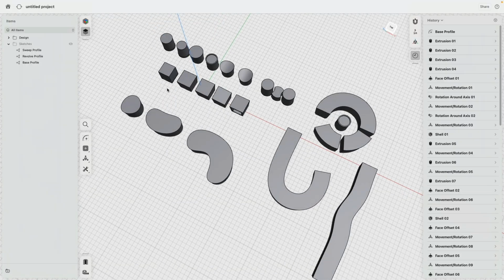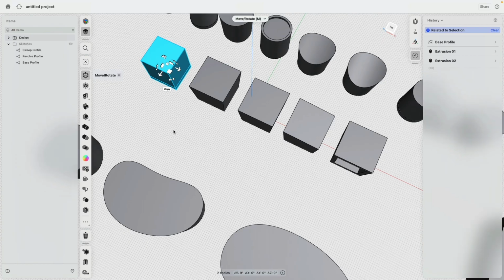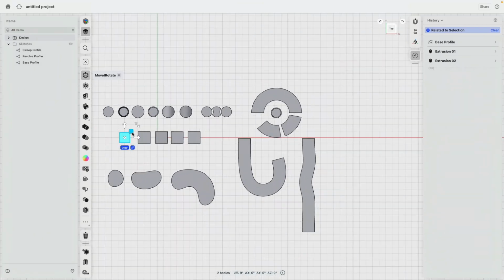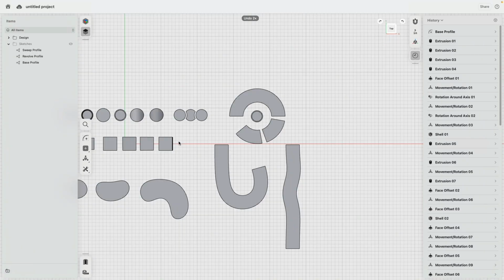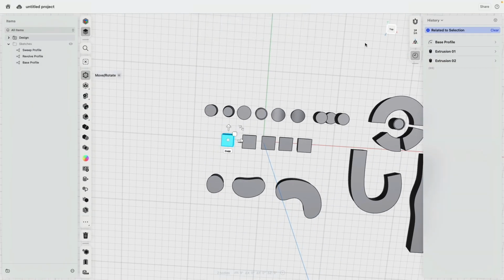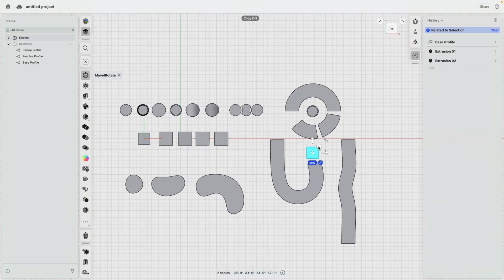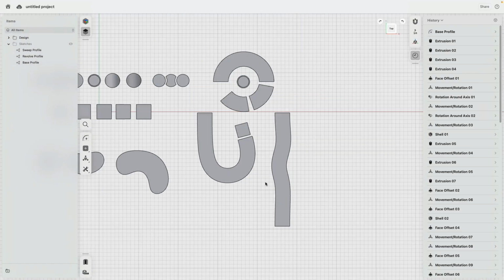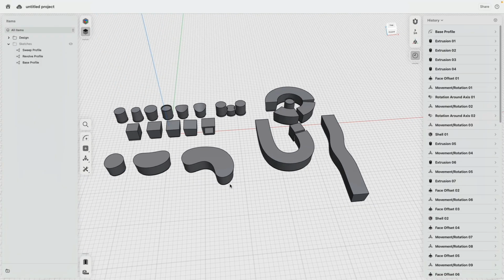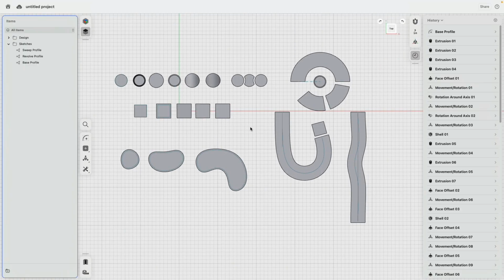That is quite nice. I might like to have this one maybe as a piece that goes to there. Make a copy, but then turn the link off. Wait, no, my fault. Let's select this one again. Make a copy, bring this over. The copy now I turn off. So I can rotate this, just eyeball it. That's fine. Yeah, that actually looks quite nice. Now you see, you compact it a little bit more. It's kind of like a drawing, but on a paper it's drawn, and then in 3D we can reorganize it. I could also simply have selected all the objects and moved them around. The way I did this now was simply that the sketches are all under the objects.